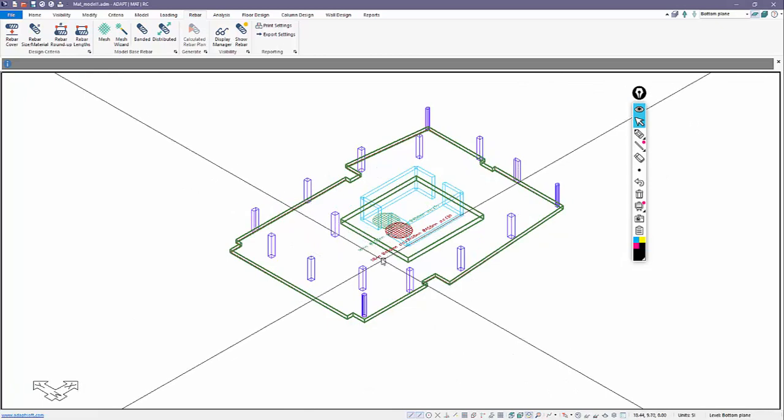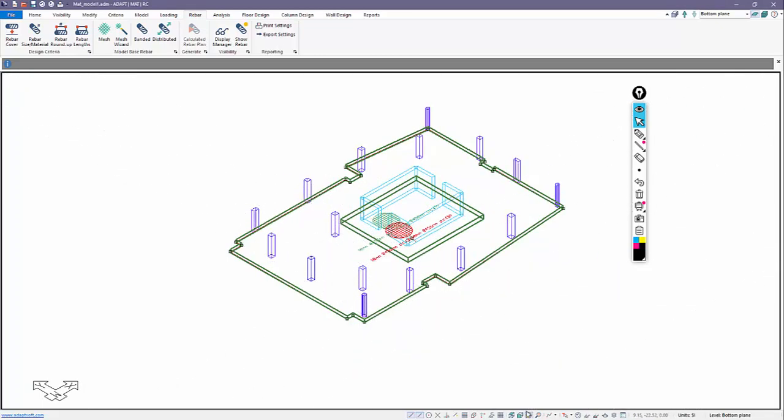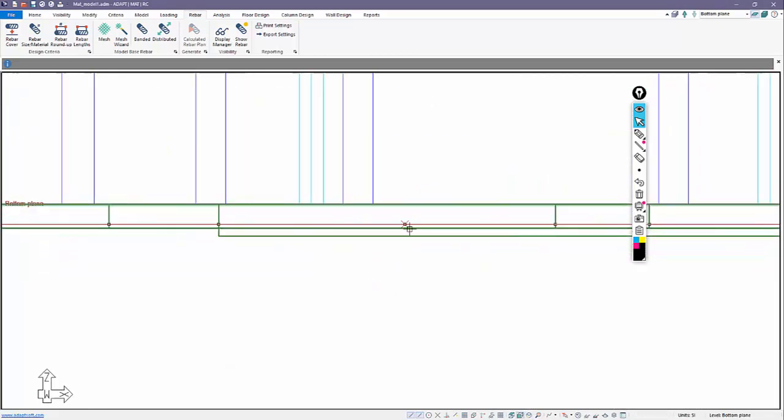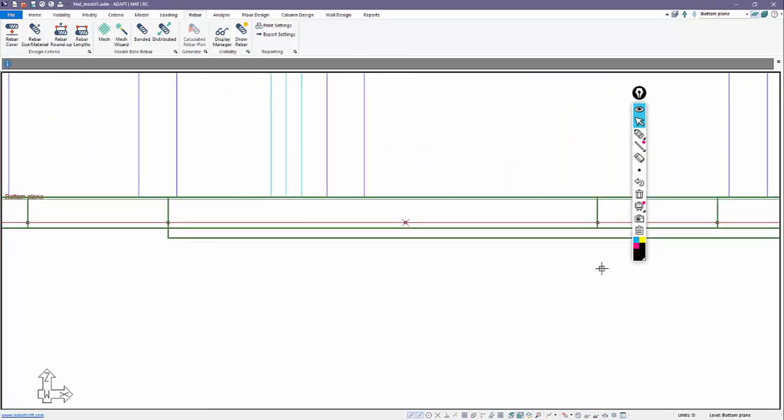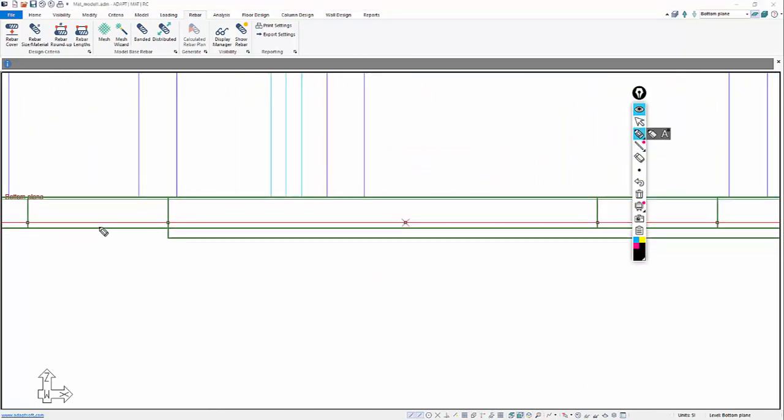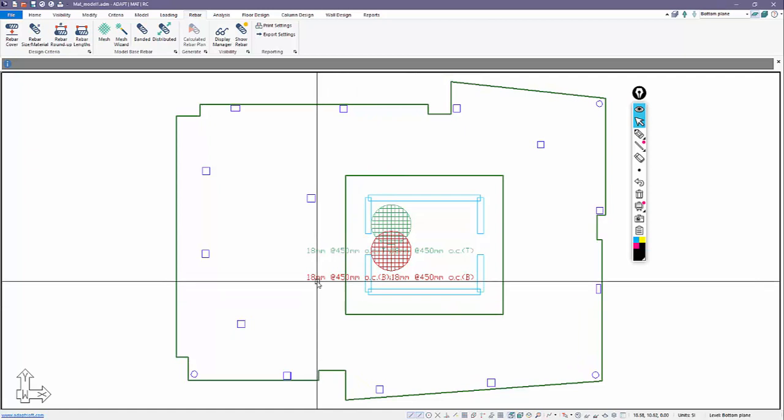And you'll notice if I look at the placement of that mesh rebar, if I go to a side view, you can see that for the thicker portion, the bar is being referenced from this slab here upward. This is the 75, 85, not from this here. So it can't break that mesh into two regions where you have two slab regions. So to get this more precise, maybe I want the mesh down here for the bottom, reference from the bottom of the thicker portion. We have to do this a little bit differently. We have to model it as adjoining regions of mesh, let's say.